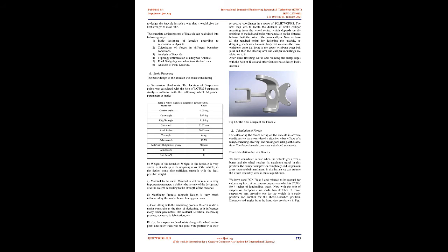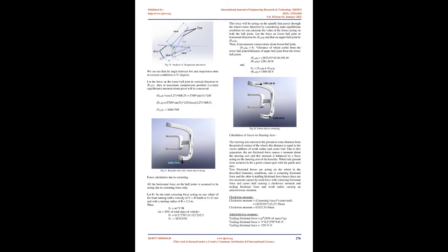Torsional analysis of the roll cage is carried out to determine the torsional stiffness to withstand off-road conditions, while taking into consideration the torsional forces acting on the frontal and rear members of the vehicle. Both tires on the front and rear axle experience a moment. The torque is applied to one tire and reacted by the other one, which is equal and opposite, hence a couple is generated which tries to twist the roll cage.